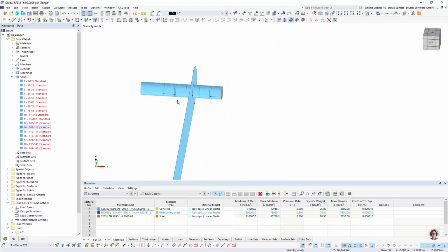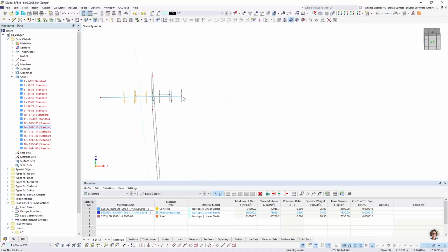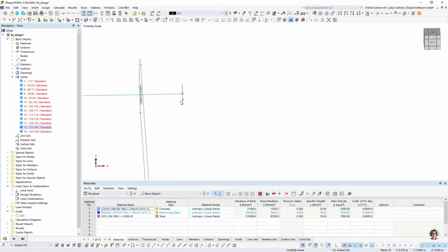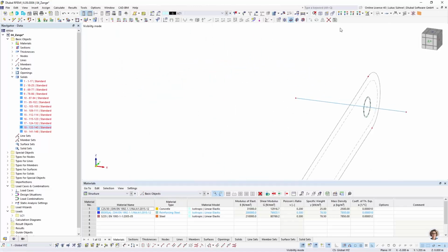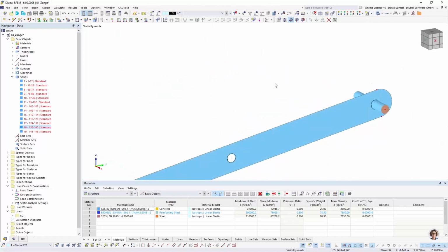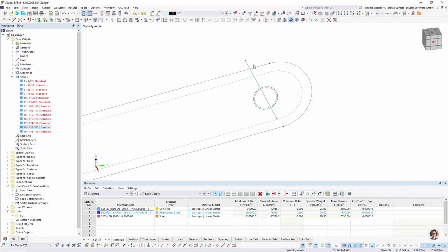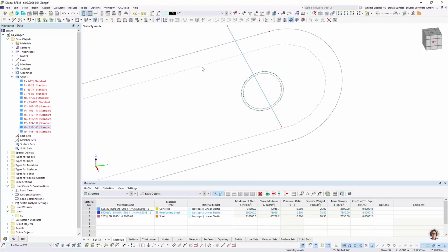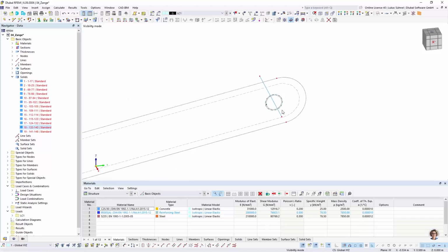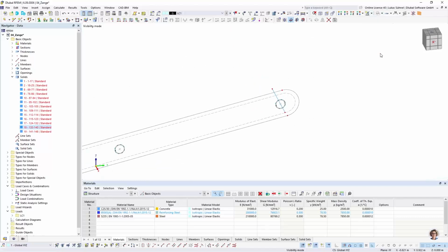with its boundary lines. And then we can change the rendering. There are some lines remaining. I can simply delete them. And I have my simplified surface and beam structure. And concerning the connection between this bolt and this metal sheet, I would use maybe a wheel of members or beams, or coupling members, to create a proper force transfer. Yeah, this would be my simplified approach for that model.